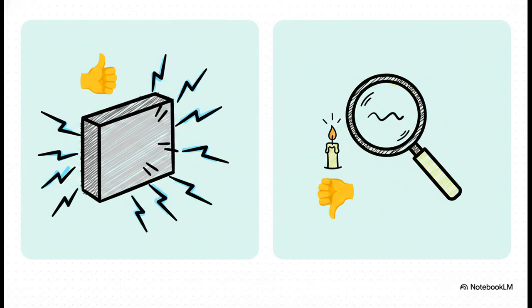When selecting a heat flux sensor, engineers absolutely love thermopiles for their brilliant stability and their low ohmic value, meaning they don't pick up much electromagnetic interference. That gives you a great signal-to-noise ratio. Also, zero input perfectly equals zero output. But the critical trade-off? Well, they suffer from low sensitivity. So if you're trying to measure incredibly subtle heat transfers, this might not be your best option.